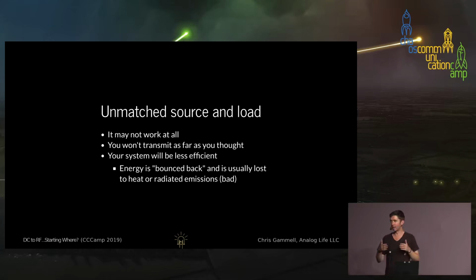It's only going to work within a meter and you expect it to work at 10 meters instead of 1 meter. And then finally, you're going to have a less efficient system as well, right? You're going to have energy that gets either radiated locally on your board and not radiated towards your Wi-Fi router, or it's just going to be dissipated as heat.